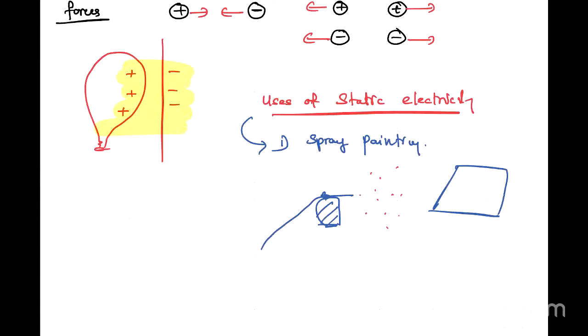So therefore, in normal conditions, we make this frame negative. How? We attach it to a negative terminal, and the paint droplets will be positively charged. So that is the first main point that you need to remember: two different charge values for the object and the paint droplet. And the next question they are going to focus on is that the paint will be sprayed in a wide range like this.